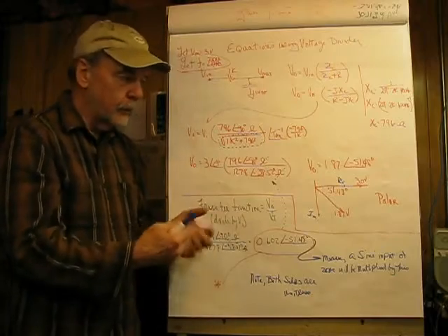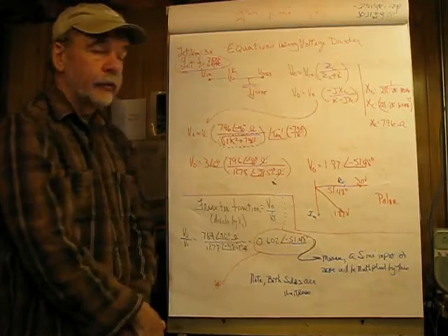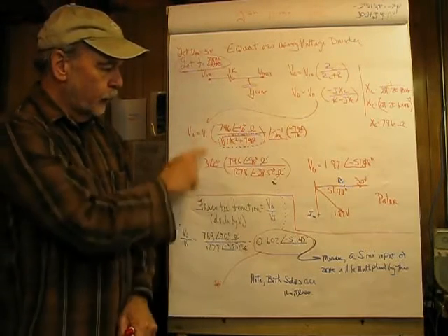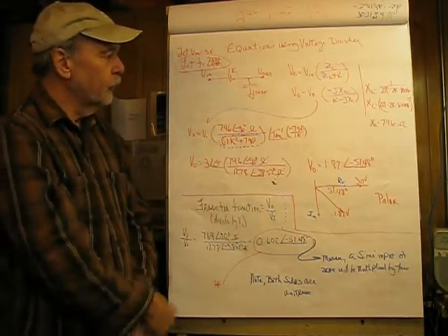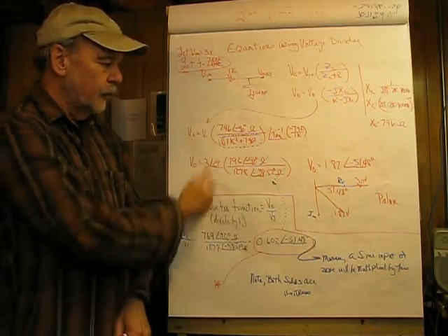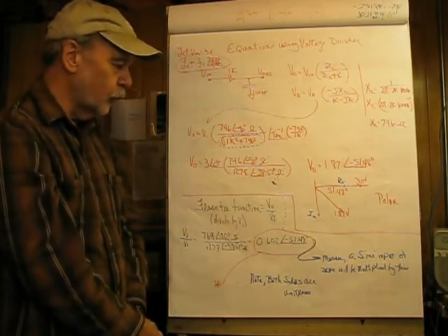It's embedded in the term. The impedance of a capacitor, on the other hand, needs to have that angle displayed. So working through this, in the numerator, the one we want across the capacitor is our 796, this time displayed with negative 90 degrees ohms.